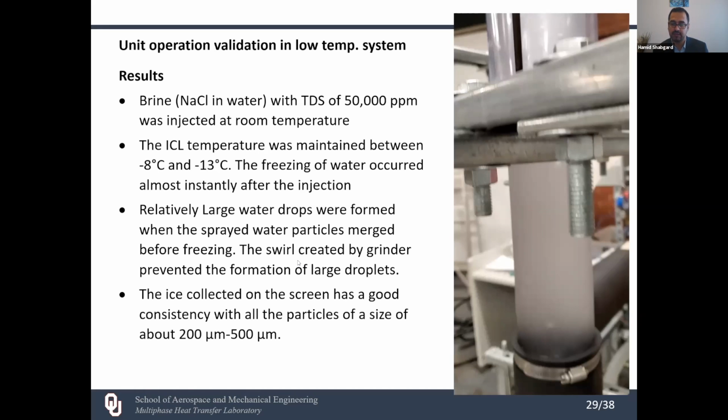So in the winter, the lower temperature outside actually would help the compressor to lower the compressor work and lower the price. In the summer, it would be the opposite effect. All the simulations here were assuming that the outside temperature is 20 degrees. We have not done a detailed analysis of the effect of ambient temperature and how it affects the total energy consumption and the cost. Okay. Very good question. Thank you.